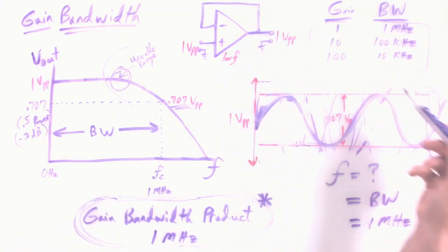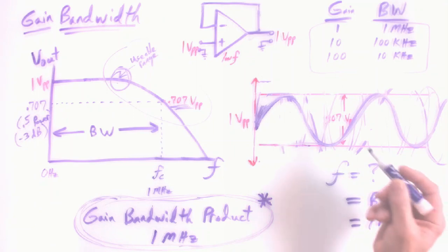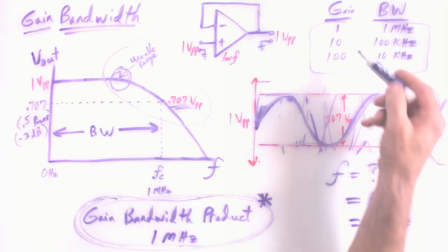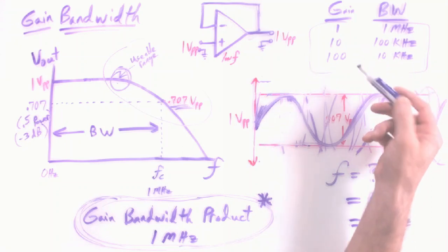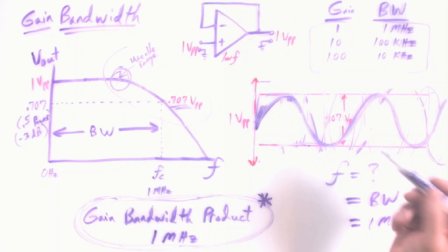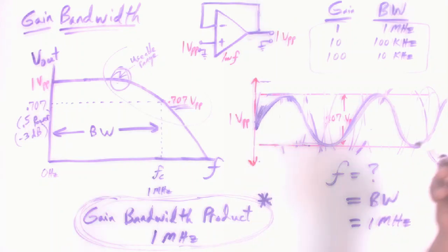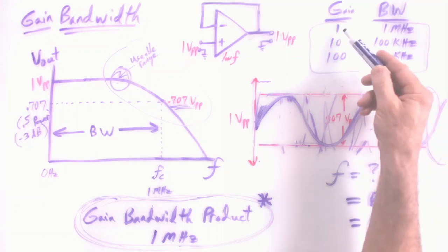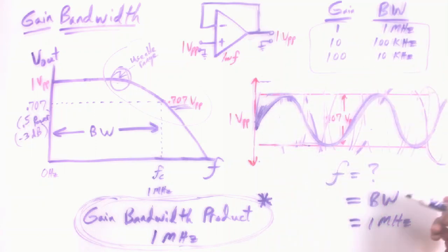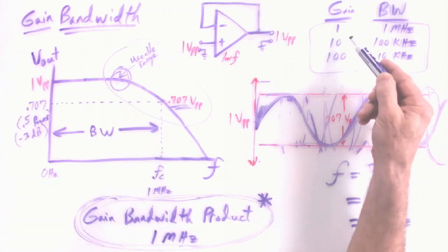You could try different gains, and we'll try that with our 358. We'll maybe try some different gains. Maybe we'll sit somewhere in 25, a gain of 25 and a gain of 50 or something like that. But that's the idea. Maybe when you're looking to measure bandwidth, a gain of 1 is probably a good idea, and it gives you the bandwidth at a gain of 1, which also gives you the idea of what the gain bandwidth product will be. But yeah, we can experiment with different gains,